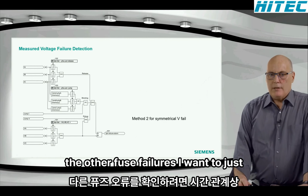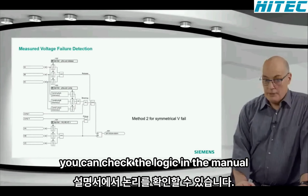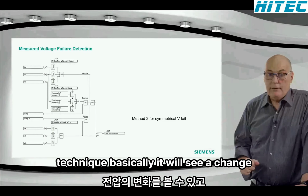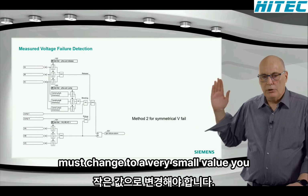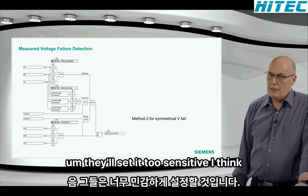The other fuse failures I want to just review very briefly due to time. Maybe you can check the logic in the manual yourself. The three-phase failure is a delta technique. Basically, it will see a change in voltage, and it's important the voltage must change to a very small value. You have thresholds that you can set. Don't set it too sensitive.